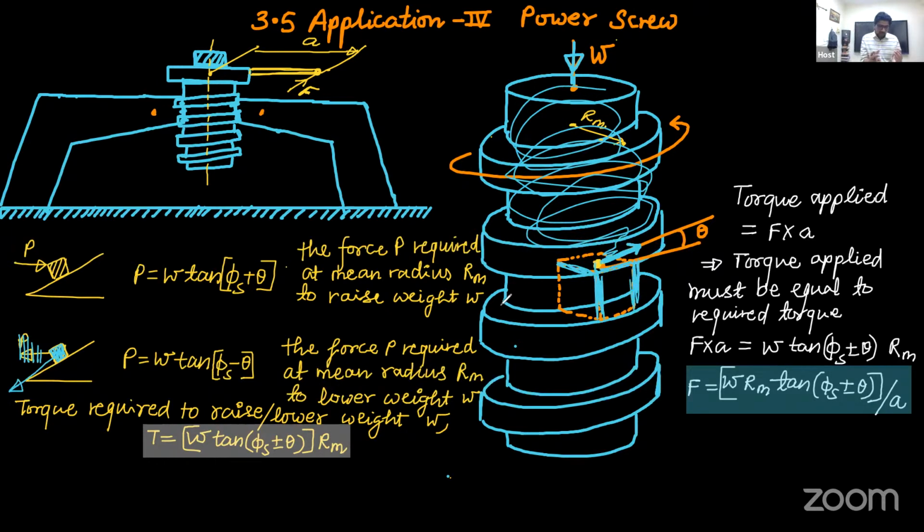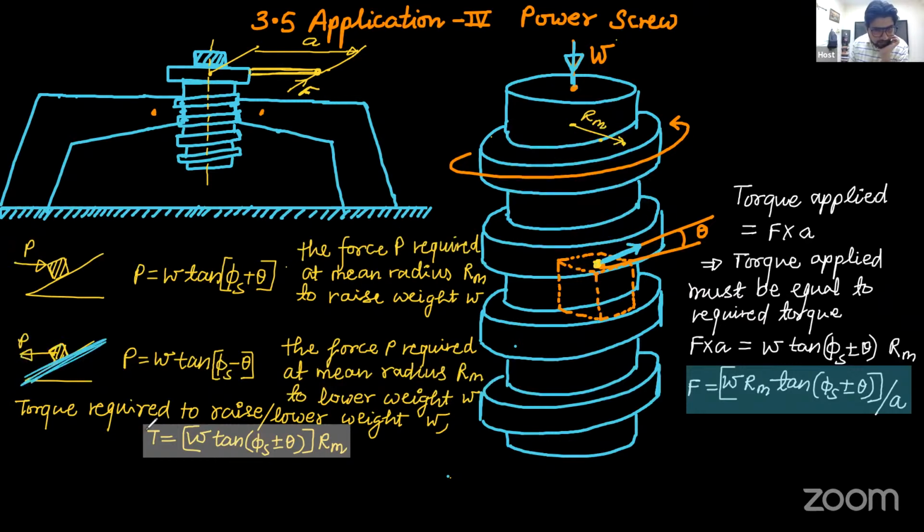Now, if you think practically, it is a dangerous thing, because if you are using a screw jack mechanism to lift the car, and the weight of the car will automatically start the screw to slip down the internal threads, it will become dangerous. The car will automatically come down, just like the weight on the inclined plane can automatically fall down due to its own effects.